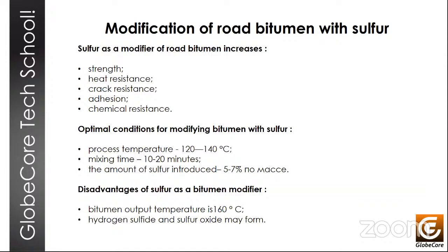And also we need to consider the increased corrosion of equipment. It was found that when sulfur is heated to 180 or 220 degrees centigrade, there is an emission of harmful, toxic gases. But if the temperature stays within 120 to 145 C, and with a sulfur content in this mix of below 20%, there is not much danger of such gas release exceeding the normal health standards. There's also the increased corrosion of equipment. As I mentioned, sulfur is corrosive, so you can expect more wear on the machinery.